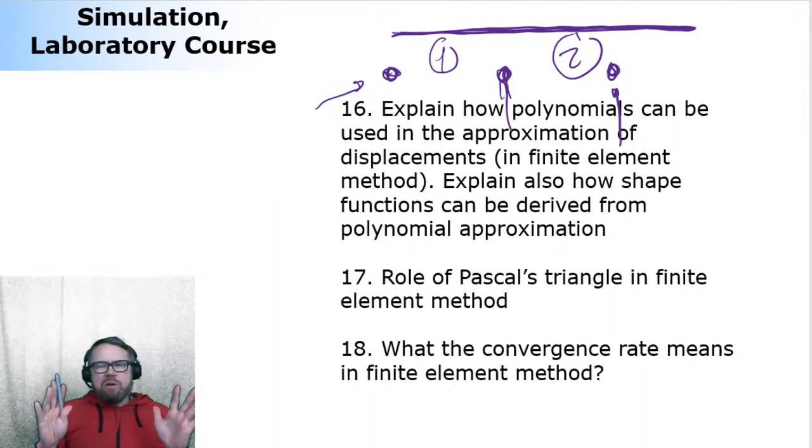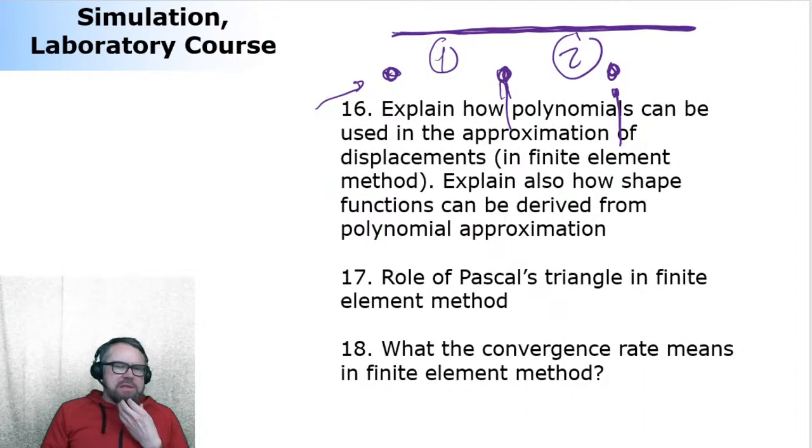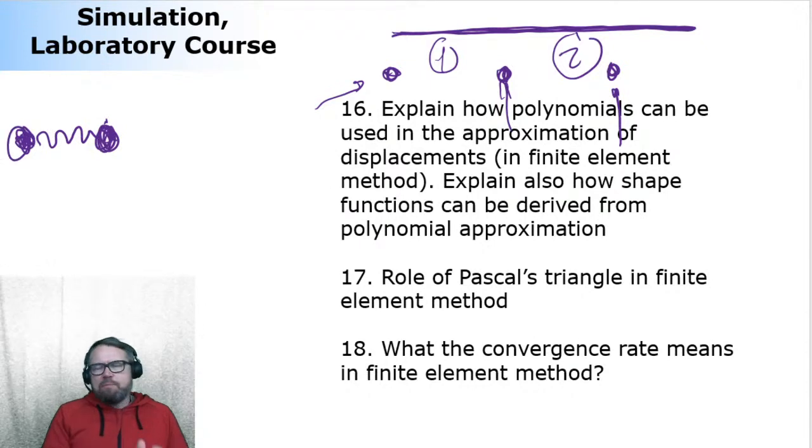Finite element modeling is all about how to describe the particles between the nodes. It's all about that. Every now and then you can hear stories that finite element modeling is something where there are spring elements between the nodes, and this behavior between the nodes can be described by springs. No, that's not the finite element method.